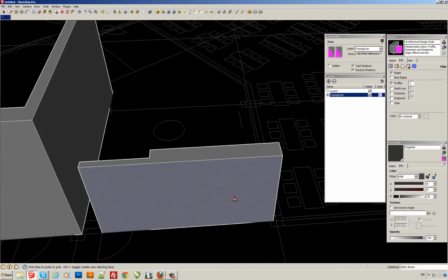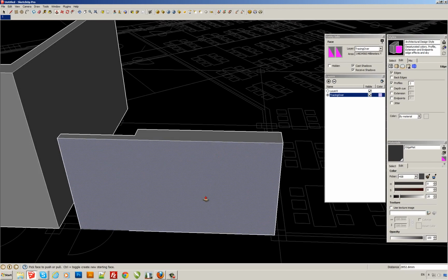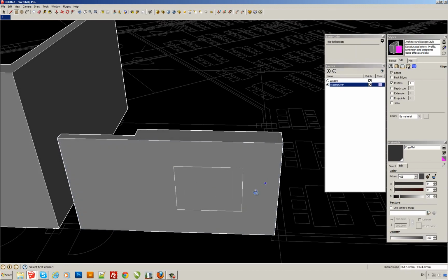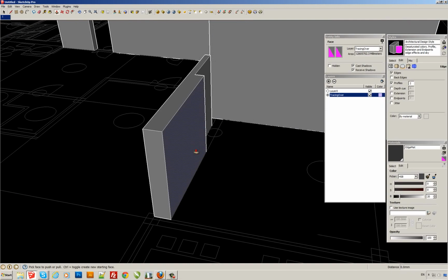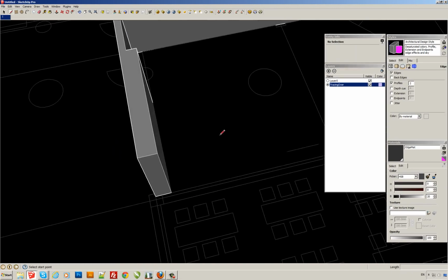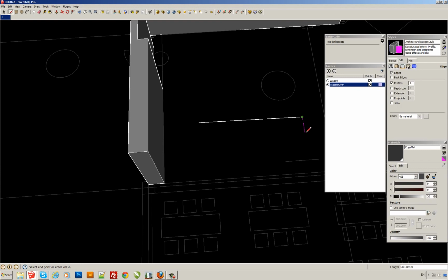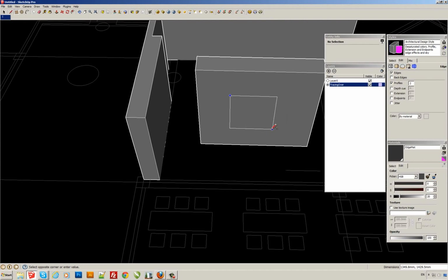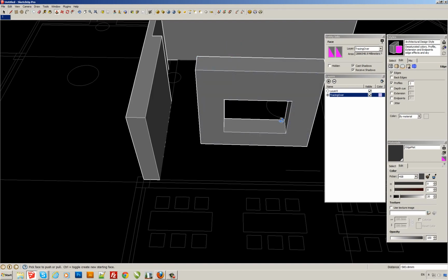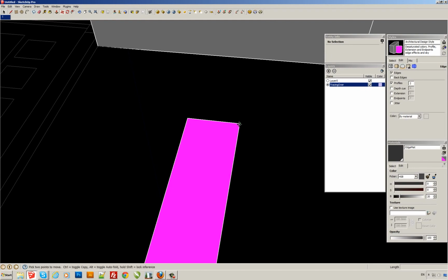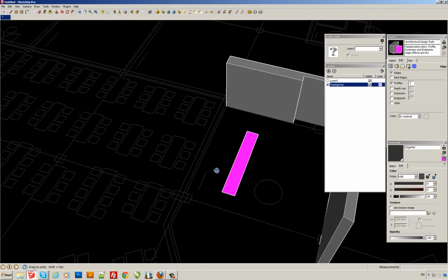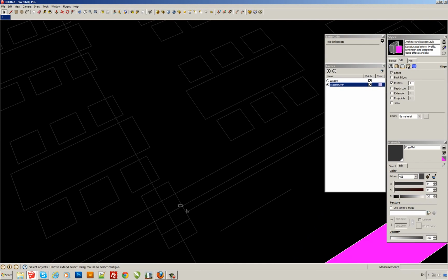To check whether the newly push and pulled wall is perfect, you can just create the window. If it works, it's created well, but sometimes it can be created like this. It happens when slightly unparalleled, so avoid snapping to the crossing point.